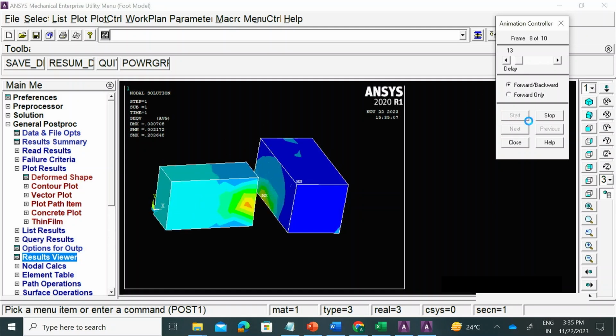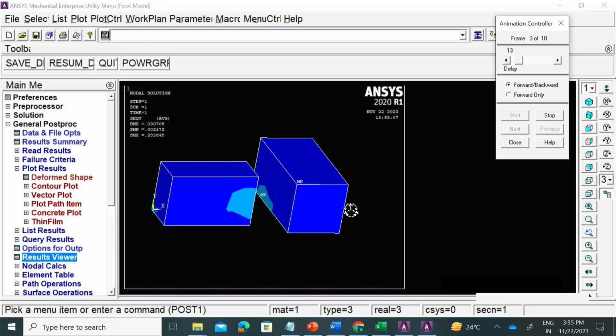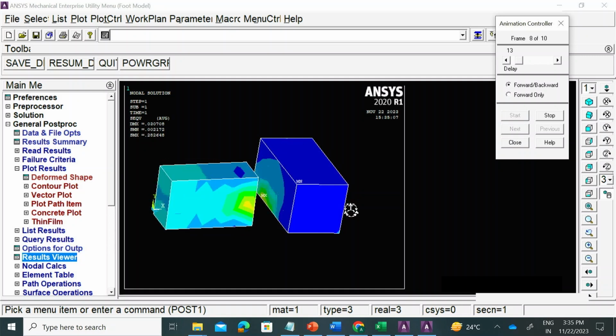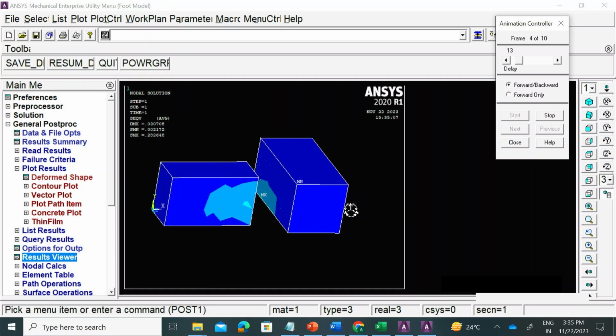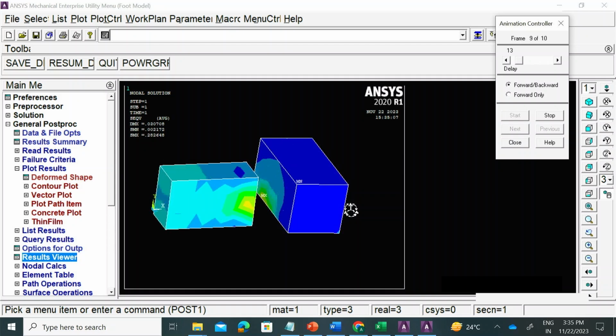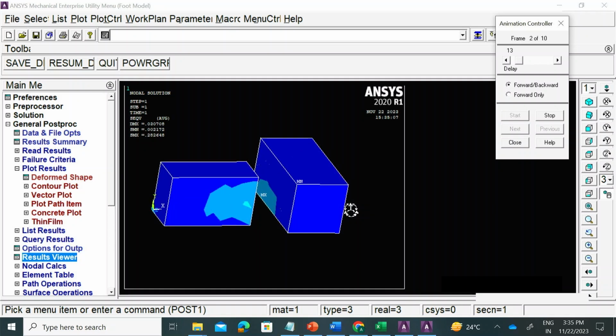Okay, so this was the second contact condition which I wanted to explain. Keep the gaps low, don't make models with huge gaps. Like I said, the rule of thumb is 5 to 10% gap size given the dimensions of the model, right? Like the maximum dimension of the model, the gap should be less than 10%, right?